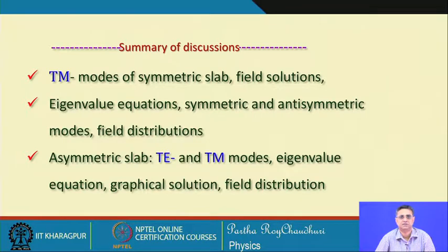We discussed TE and TM modes for the symmetric slab waveguides, and also tried to depict the field solutions, the profile of the field distribution. In the process, we evaluated the eigenvalue equations, symmetric and antisymmetric mode fields.